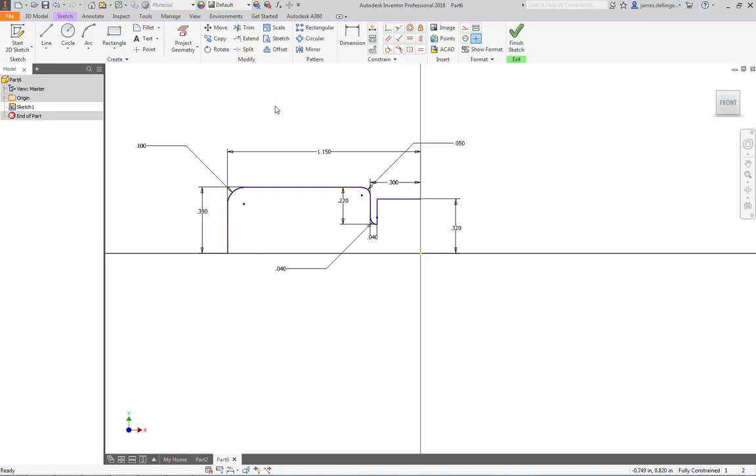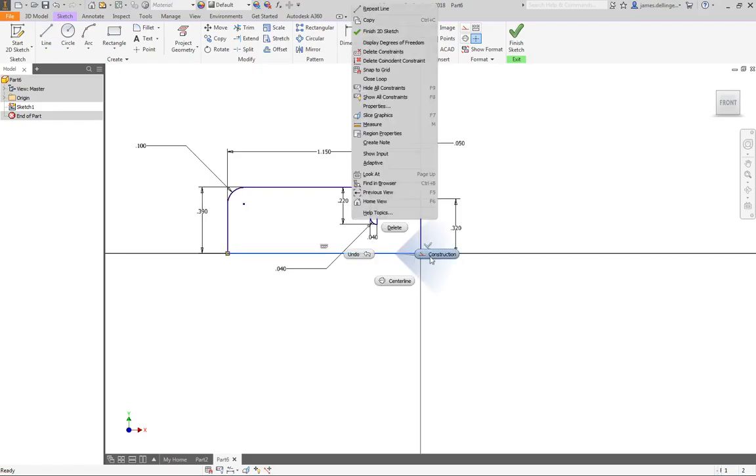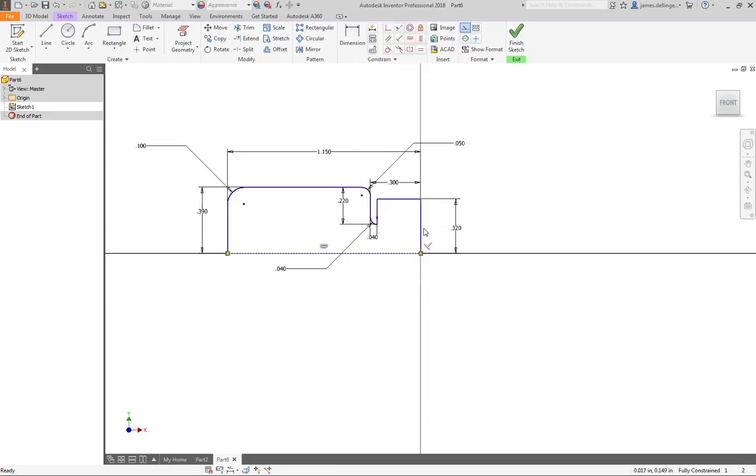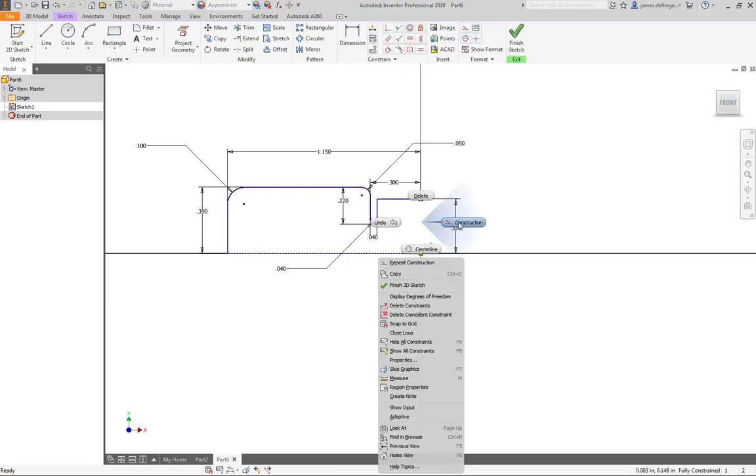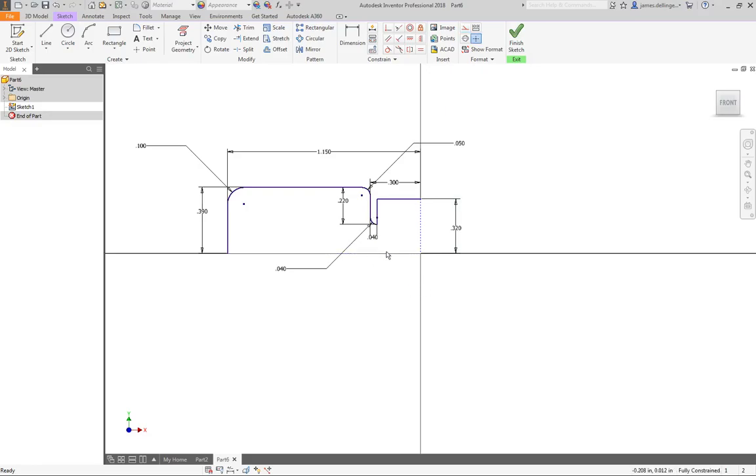this around. And the easiest way to do that is to go ahead and draw the lines in there. So I can pick these lines from here to here, and I can pick from here to here. Now, I don't need those to be object lines. I need those to be construction lines. So I can just right click and say construction. And so those will be my axes that I'm going to mirror around. So then now we just go back to the mirror command.